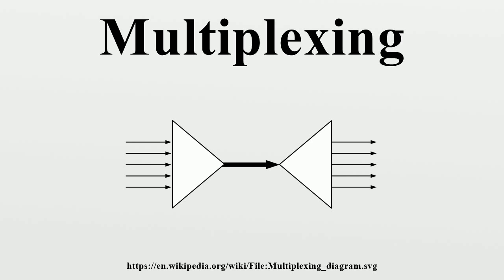Digital broadcasting: in digital television and digital radio systems, several variable bitrate data streams are multiplexed together to a fixed bitrate transport stream by means of statistical multiplexing. This makes it possible to transfer several video and audio channels simultaneously over the same frequency channel, together with various services. In the digital television systems, this may involve several standard definition television programs, or one HDTV, possibly with a single SDTV companion channel over one 6 to 8 MHz wide TV channel. The device that accomplishes this is called a statistical multiplexer.